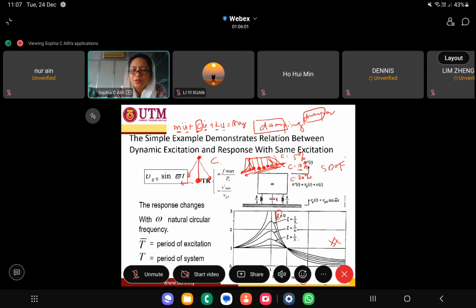So this damping's job is to reduce the vibration. If your damping is 0, eventually it will reduce, but very, very slowly. This is the curve where the damping is 0. It doesn't give you a value because it is infinite, it's unknown when it is going to stop. But if you have damping of 1/5, it is going to reduce your amplification factor to this much. And if I increase my damping to 1/4, which is 0.25, it's going to be until here. That is my amplification factor.